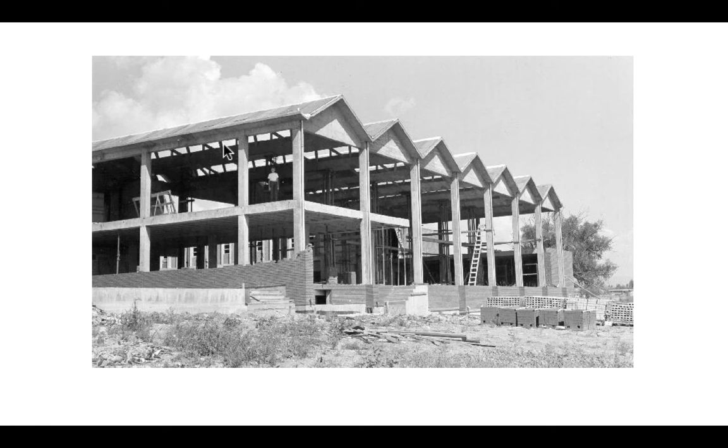And that, again, takes some of the principles we were talking about last time, right? The hacked beam, the castellated beam, taking material out from around the neutral axis, leaving what are essentially the flanges of the folded plate, the top and bottom fold. So taking away some dead weight that's not doing very much, and at the same time introducing some daylight into the space below.